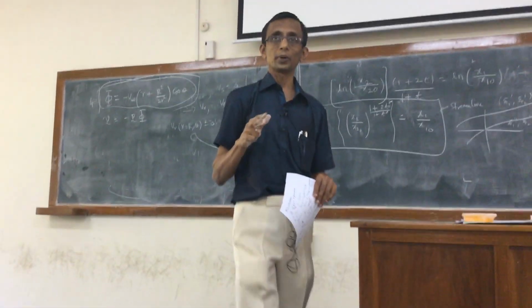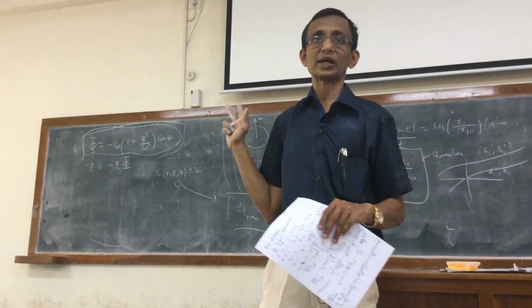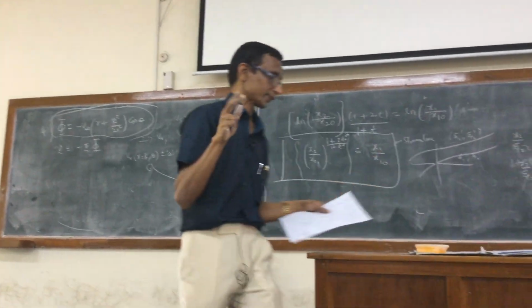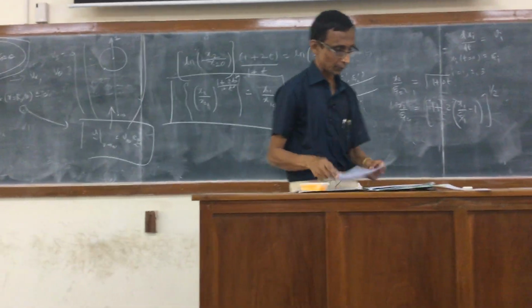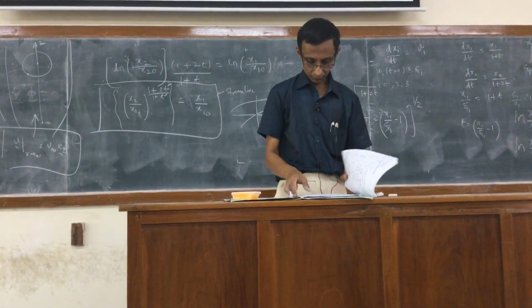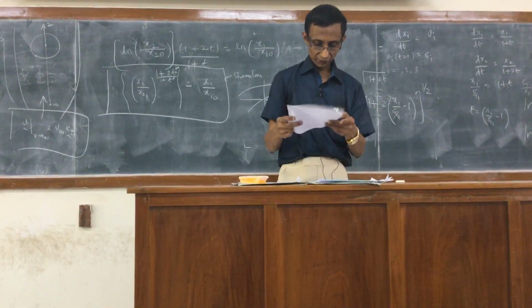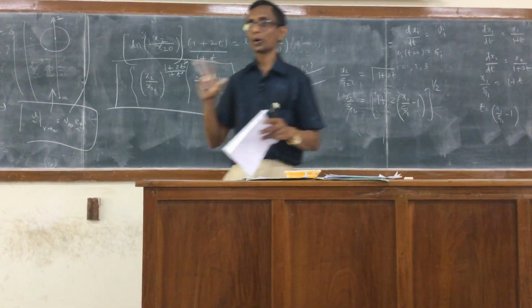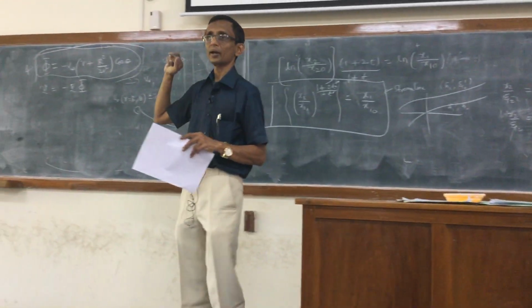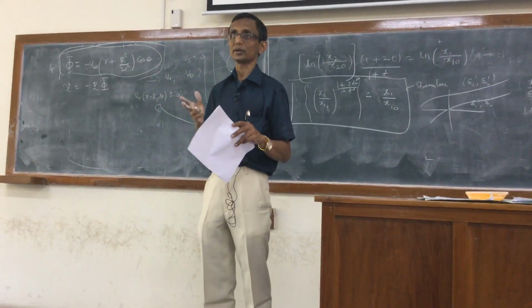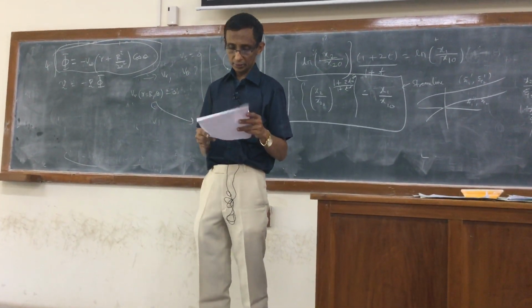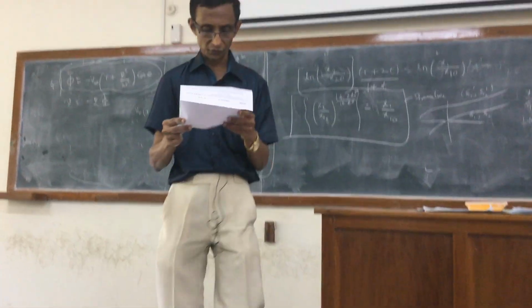You can apply the Bernoulli equation. Only for a perfect fluid can we get the pressure profile that is given. So you have to assume that, which is probably stated in the problem. It's only for a perfect fluid. So it's the same problem that we have solved for the cylinder. We have to go through it for the sphere and get the potential as well as the pressure profile.